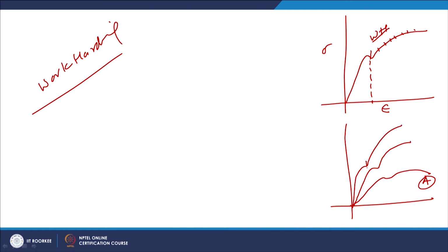Since after the deformation, especially once the plastic deformation sets in, this slope indicates the rate at which the stress requirement is increasing to cause further strain, the slope of the curve in the plastic strain zone indicates the rate at which the material is getting work hardened.